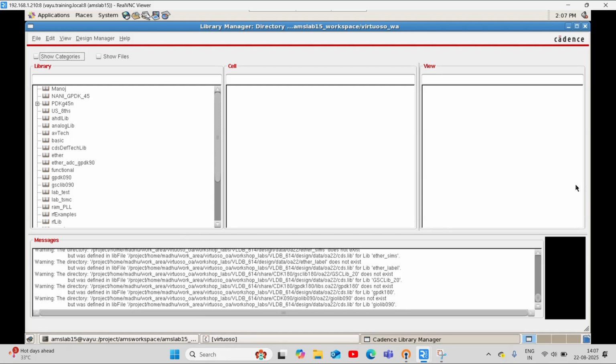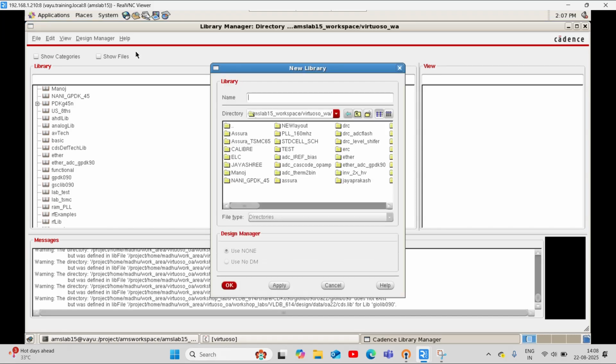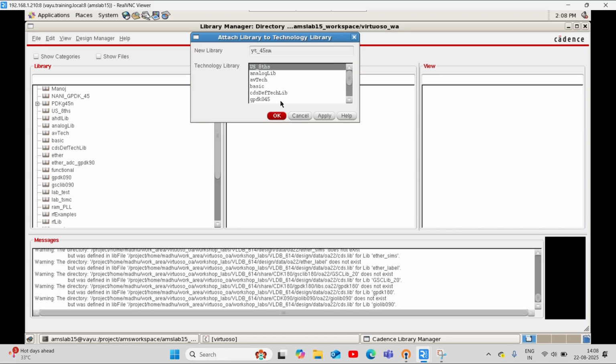So for our channel purpose, I am going to create a new library, and the new library is going to be YT. We are making it in GPDK 45 nanometer, so I am keeping 45, and I am attaching the technology library.